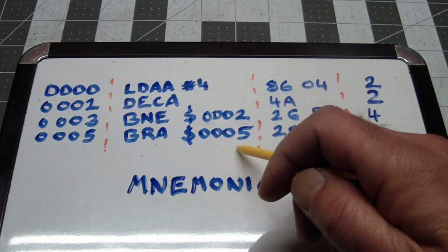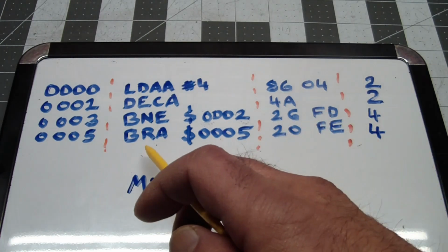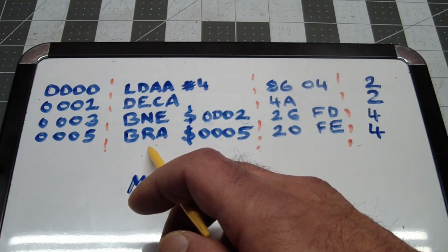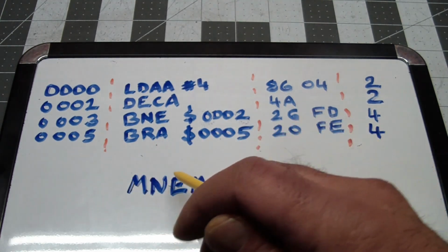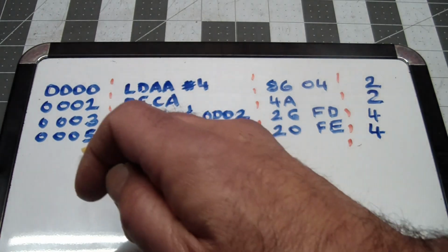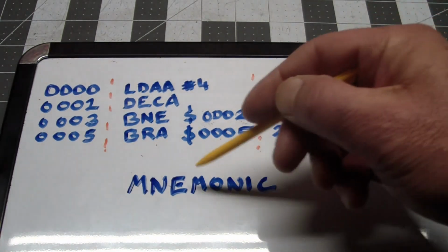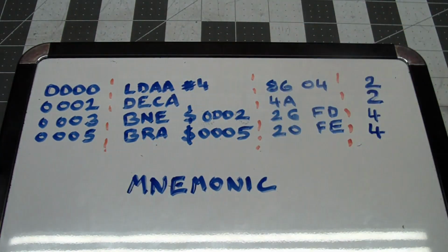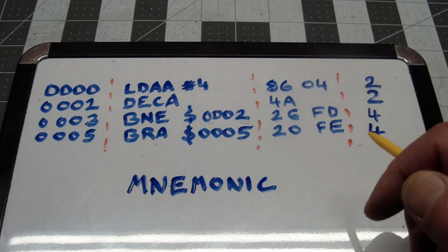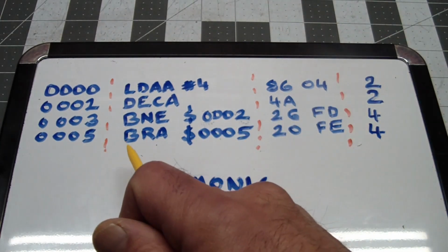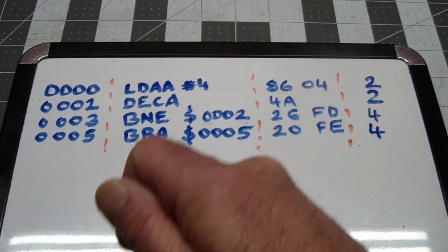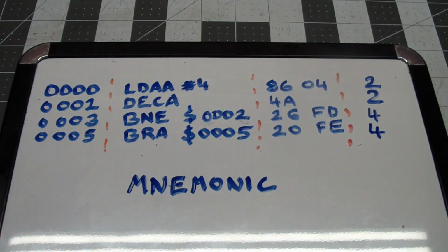This is basically an infinite loop. What we're saying here is we have branch, which means unconditional. It doesn't look at any of the condition flags, and what it does is it just keeps branching back to itself. It's chasing its tail. But the reason you do that is you don't know what the contents of RAM may be after that, and the program may try to execute things, and it'll just keep trying to execute stuff. So it's always a good idea when you have short programs like this, test programs or anything, to have an infinite branch at the very end so the processor doesn't go bananas.